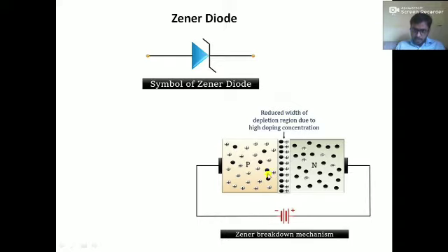So what happened, it is heavily doped, so the number of free electrons is high. The solid black dots indicate the free electrons, and these are the free charge carriers in the N region, while the holes are the minority charge carriers in the P region. Keep it in mind, there is always a minority charge carrier present in the P region, and also in the N region.